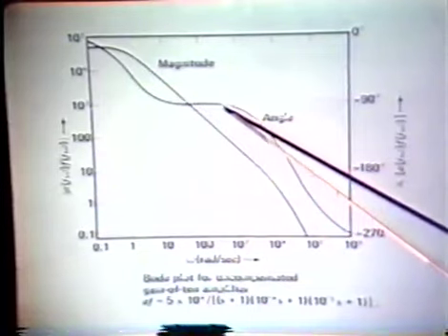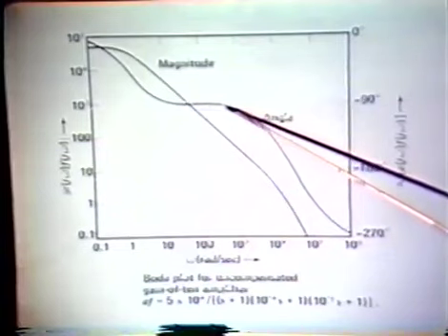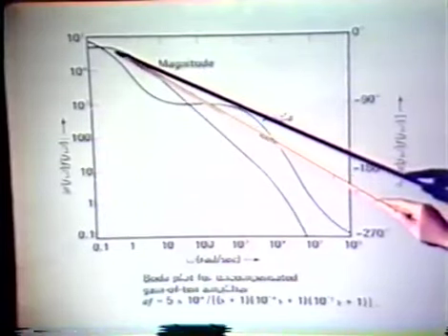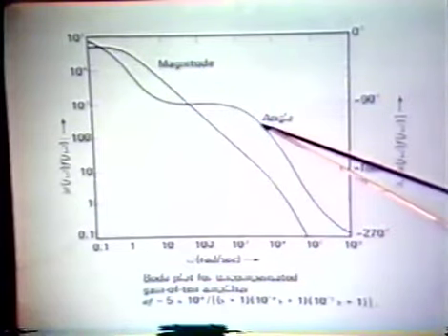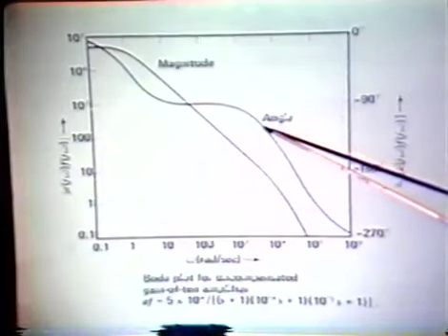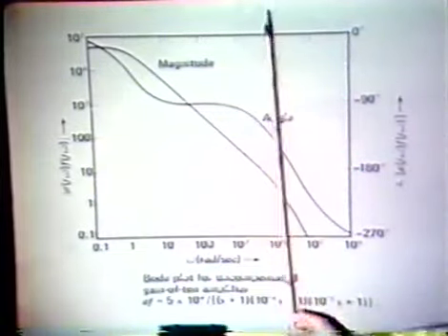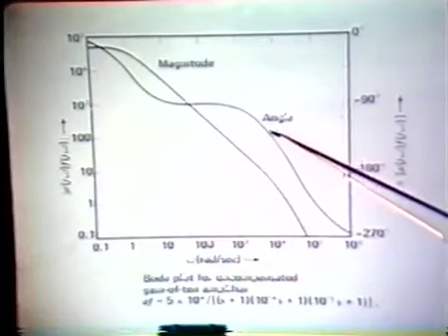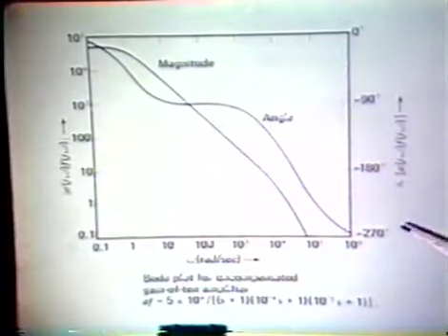We then go through a relatively wide range of frequencies where the angle stays close to minus 90 degrees, reflecting the phase shift associated with the first pole. Out at about 10 to the fourth radians per second, we pick up an additional 45 degrees of negative phase shift. So here we're down to minus 135 degrees by 10 to the fourth radians per second. The angle then continues, asymptotically, of course, reaches minus 270 degrees in our particular example, since we have 3 poles assumed associated with the AF product.